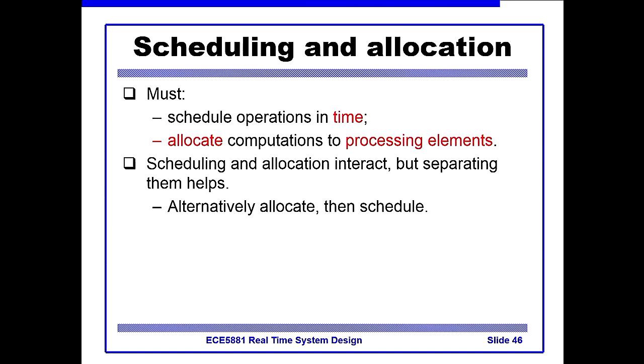All right, so let's look at another scheduling problem that's related to this multi-processor environment. So what we're going to do here is look at an example where we do time and physical scheduling. So we're going to schedule in time and also in terms of allocating hardware to particular functions. So that's a spatial dimension as well. So time we've already covered. We've looked at scheduling with RMS, for example, and EDF and so on, but we haven't actually looked at the problem of allocating dedicated hardware to particular functions in the same problem.